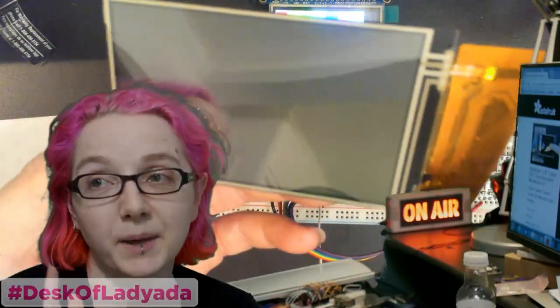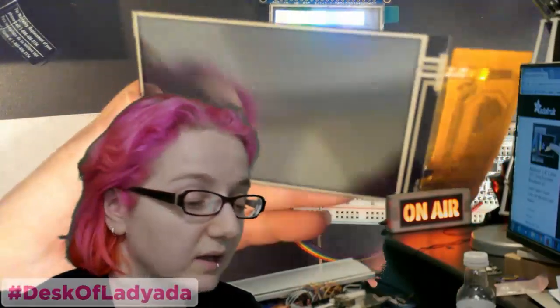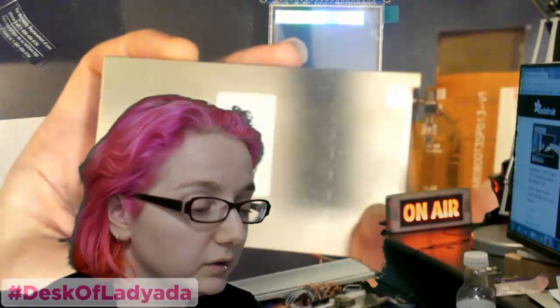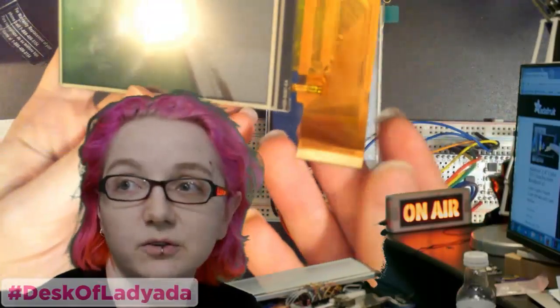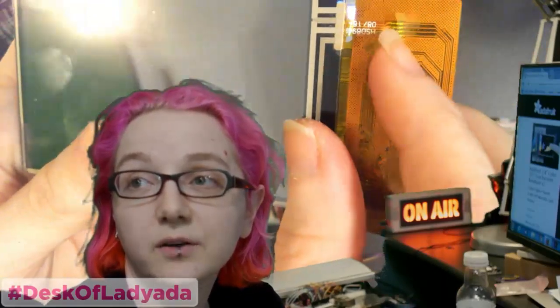What's interesting about touchscreens is that they are completely separate from the display underneath. So this is a display module, and it has all these connections for the display. And if you look at the resistive touch, if I get really close, you'll see these 4 tabs come out here, and then they solder. There's a separate cable that solders onto this main flex PCB, and these pads just go to the last 4 pins of this connector.